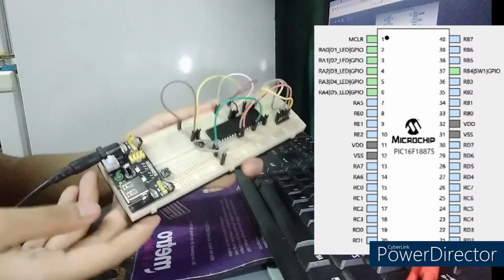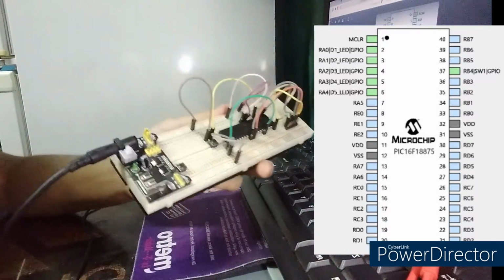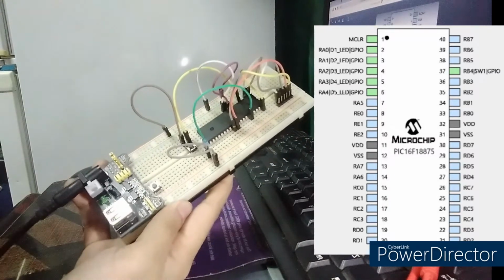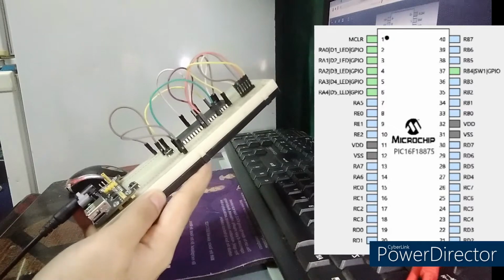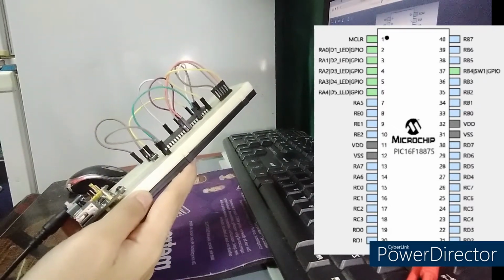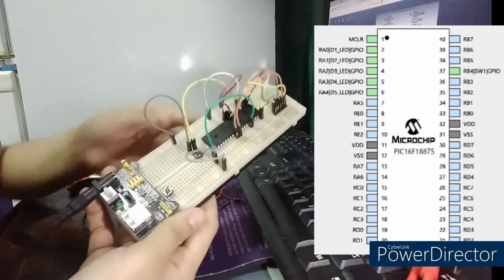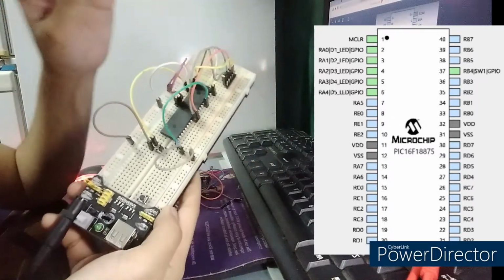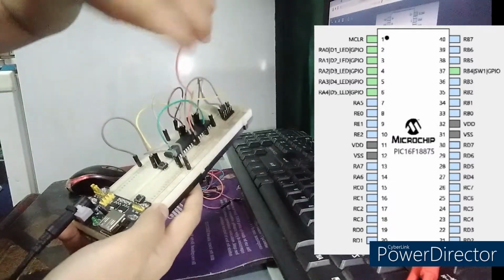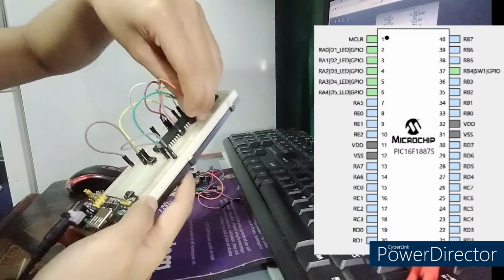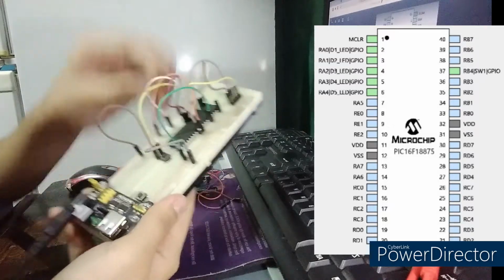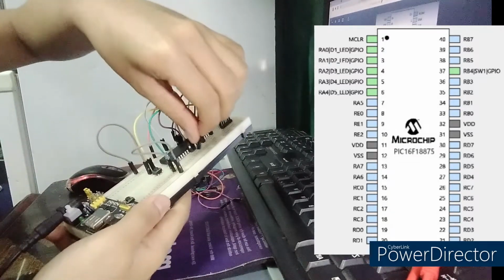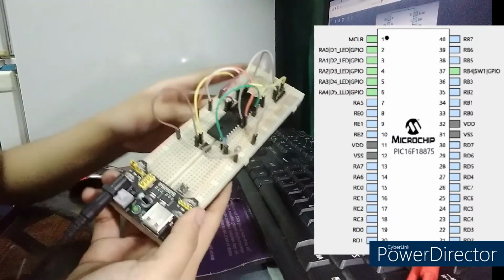And we will now be modifying our circuit wherein we will be adding an additional 4 LEDs on our IC pin. As you can still remember, we selected 5 LEDs as our output, which is connected to pins number 2 to 6 of our IC. But first, let me get this wire and connect it to the positive polarity of our voltage supply, and this wire, which is our VSS, should be connected to our ground. Okay, so now let's start connecting our LEDs.